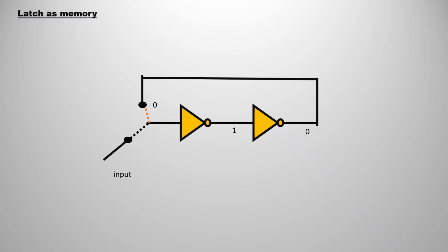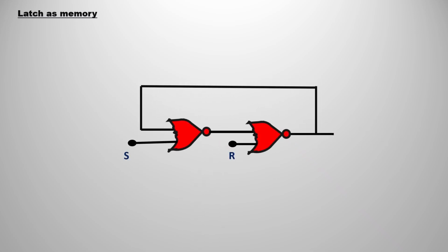So we are going to use a circuit with two inputs, and with the help of a NOR gate we can implement that. If you use NOR gates, we can implement the memory element like this. You can see the first input is S and the second input I took as R. Here S means set and R means reset. The final output is cascaded back to the other gate. That is known as feedback.